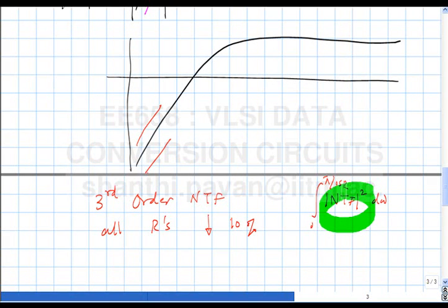Please note that we discussed, you cannot get good in-band behavior without losing at out-of-band frequencies. So if you got 30% reduction in the in-band quantization noise in the third order case, it must follow that the out-of-band stuff is going out of control, the area above the 0 dB line is increasing by 30%.